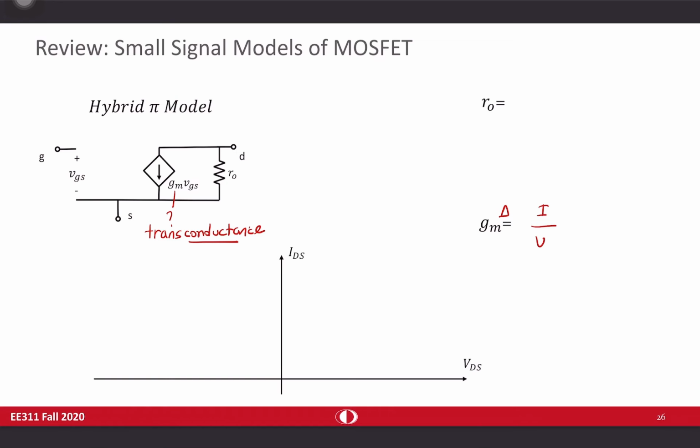I is the output current, which is ID. V is the input voltage, which is VGS. Again, you have to use partial derivative in here. Now it is a bit easier because it's going to be del divided by del VGS times Kn divided by 2 (VGS minus VTN) square. I am using the saturation current expression. Why? Because to be able to deal with a small signal model, your MOSFET transistor should be in saturation. That's why I'm using the saturation current expression.